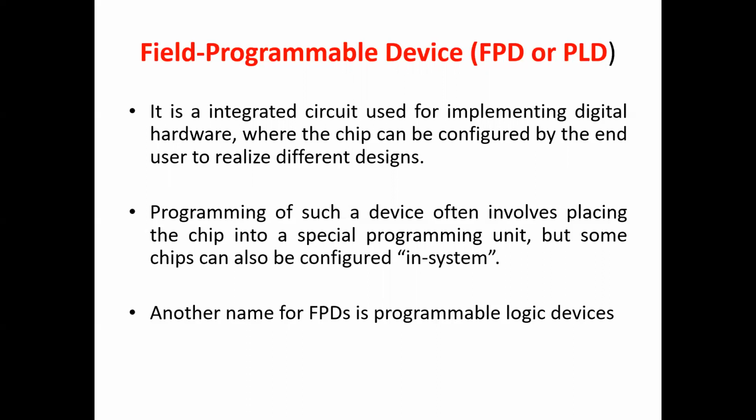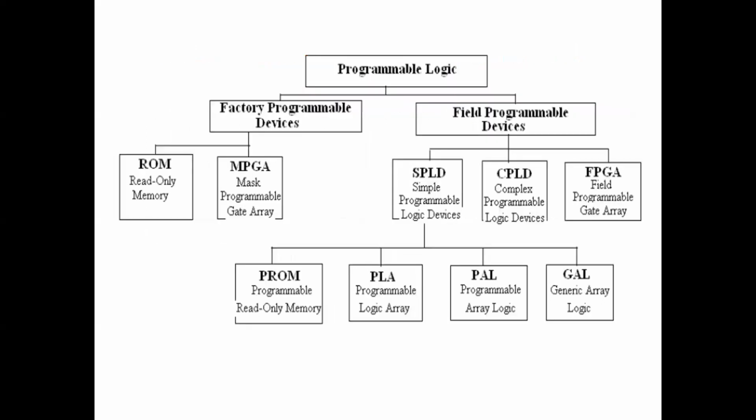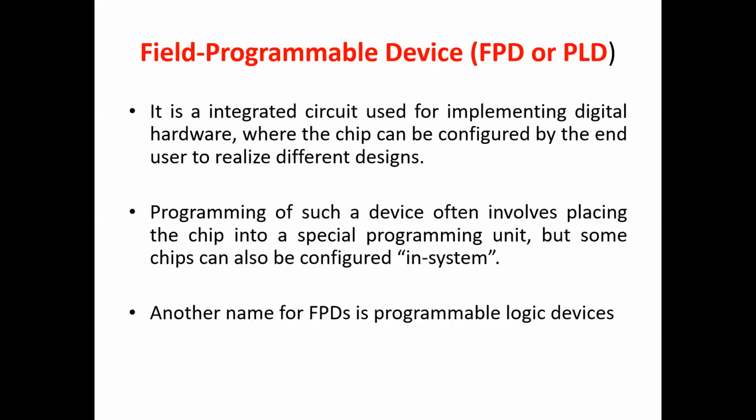See, if you have done the HDL lab, in the HDL lab we have programmed this. Whatever program you write, your Verilog program or VHDL program, you dump it into the FPGA kit using flash, and then you check all the outputs. That LED glowing according to your gate or all that, you check in that.